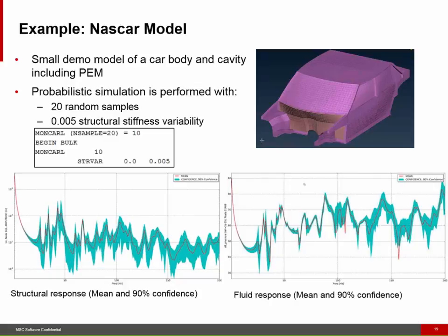And then you can post-process this, the probabilistic results, like the mean value and confidence interval, 90% confidence, both for structural and in this case also for the fluid. So it shows that already from fairly low frequencies there's a significant influence from the variability on this particular model.